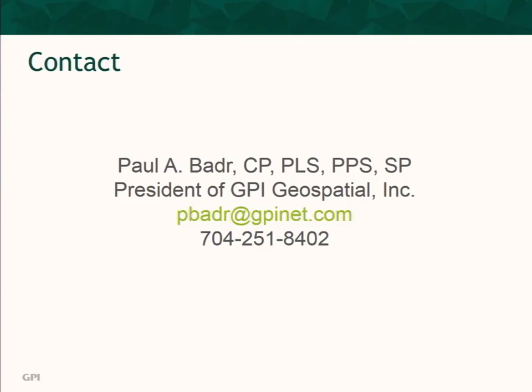Any other questions? Edge of pavement is very easy. If it's a clean edge of pavement, it's fine. If it's an irregular edge of pavement, it's going to try to show you exactly where the edge of pavement is, and then you might have some lines that are not straight, so you have to take care of that too in the CAD environment. Nobody wants to see a road that's doing that, even though it is. It's so accurate that it is following the edge of pavement.